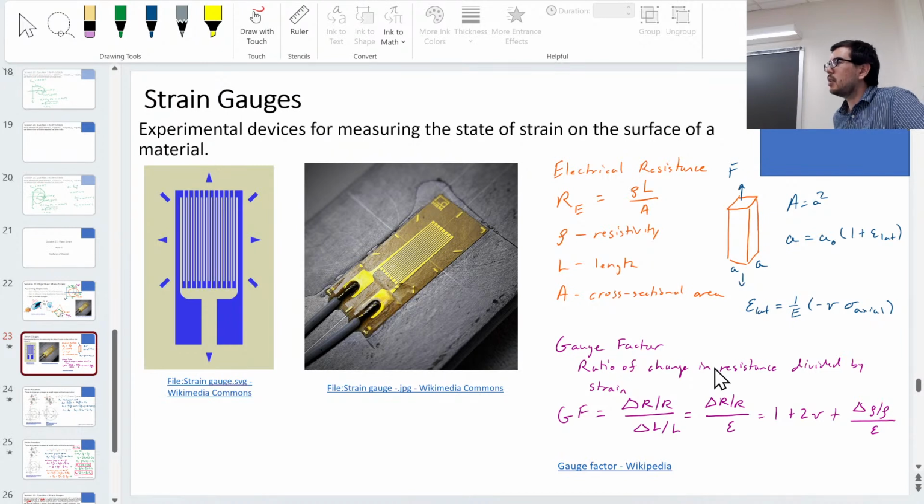Okay, so you can, yes? Does the adhesive limit the straining of the material? Sure, yes. If you had a really thick adhesive, and imagine that the elastic modulus of your adhesive was super high, and it was super thick. Or actually you could imagine if it's super low, that probably is a better situation. Like if I put a strain gauge on a piece of rubber, and something strains underneath it, then I'm going to have no ability to measure what the strain is above, right? So you want to have really good intimate contact, almost like rigid contact, so actually a very high elastic modulus if possible, so that the strain gauge feels the strain that the object is feeling.